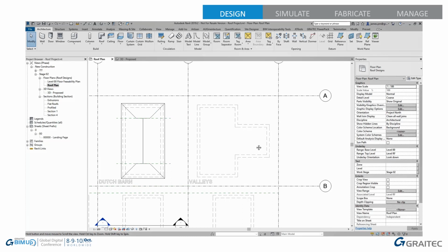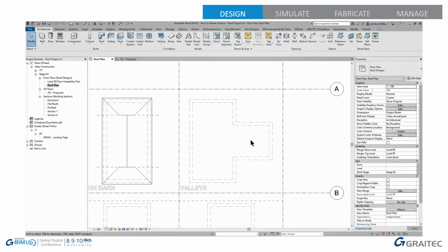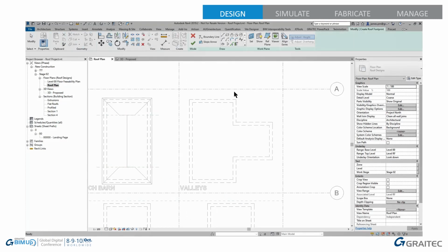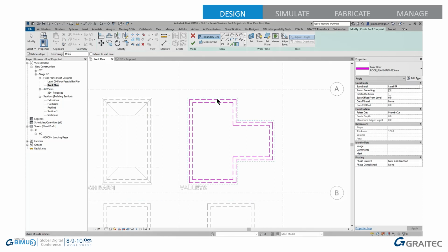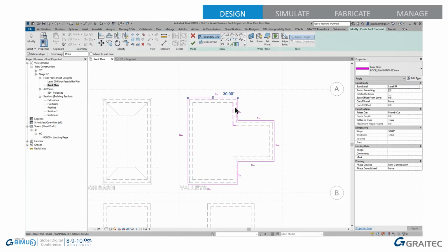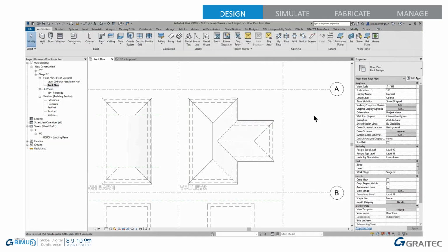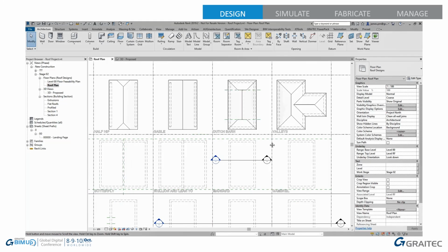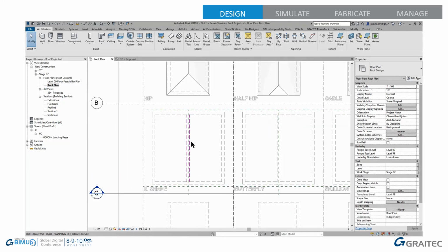Let's go back to our roof plan and a valley roof. Now doing this again is very similar to what we've done so far. I can hit tab at this point and select all of my walls because they're all joined up. Now basically because each line will slope perpendicular into the middle of the sketch, once you complete it, it will form a valley and hip roof really easy. It's one of the easiest things to do.